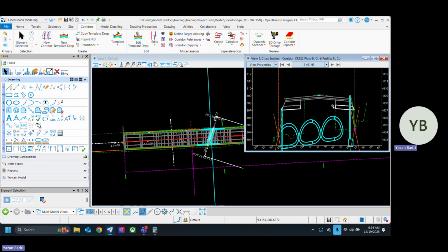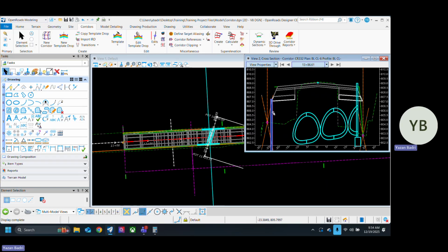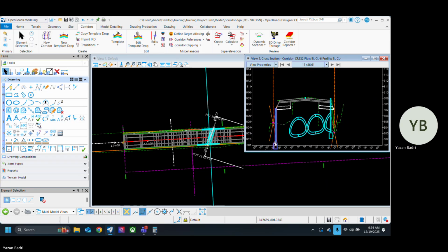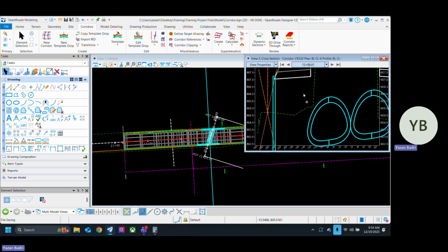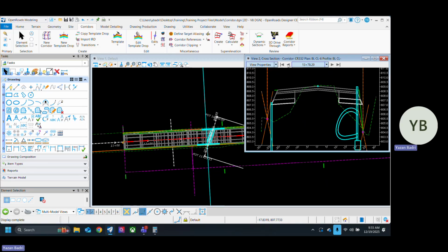Seems like we need to use a higher head wall or raise the flow line a bit. Seems too low here. But on the skew, it looked okay. Like when you look at it perpendicular, it looks off, but at the skew, it looks fine. That's true. I think they ended up leaving us with like 1 foot of cover.